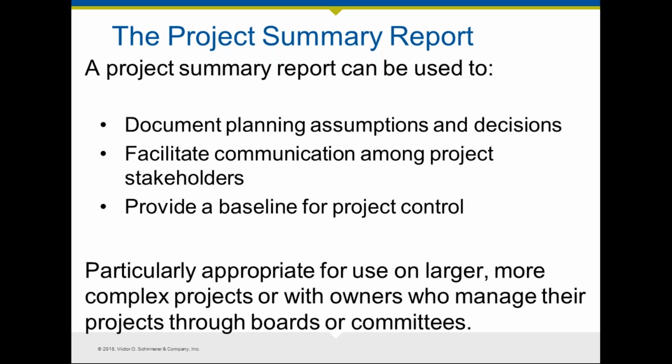So the summary report should have your program, obviously, the schedule, any milestone dates that you've agreed to that are within your control, that are the targets, the owner's construction budget, and any contingencies that they may have budgeted for that, an opinion of probable construction costs that you've provided based on the program description, that obviously will be refined further when you do the design services, the owner's strategy for procuring construction services, owner furnished site data and information, or what the status is on that.